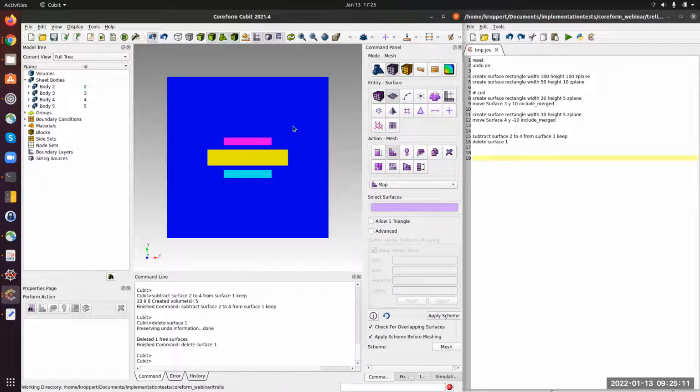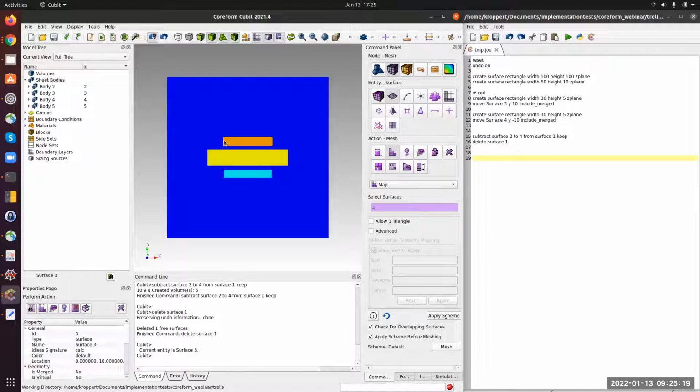And the issue is that we cannot out of the box mesh this blue region, since with this map command we can only mesh 4 noded geometry, 4 noded quadrilaterals. So the coils and the surface, they could be meshed with the map algorithm right away.